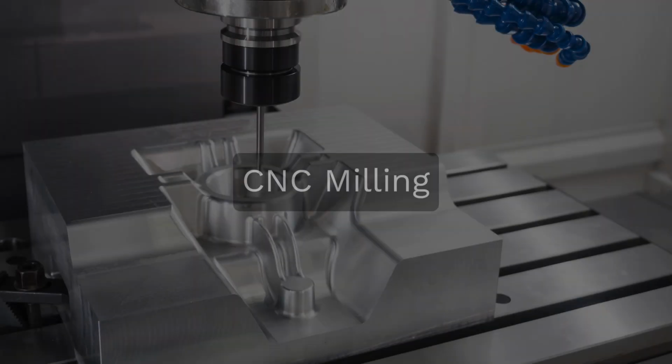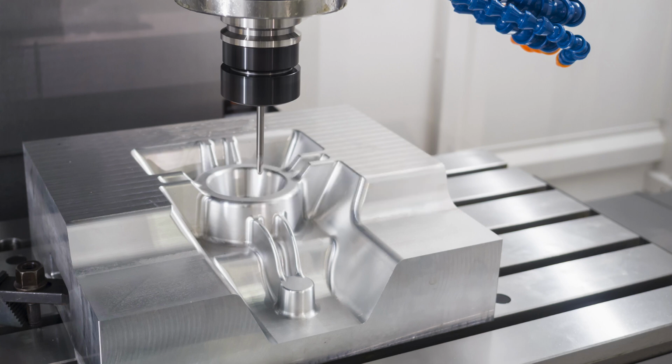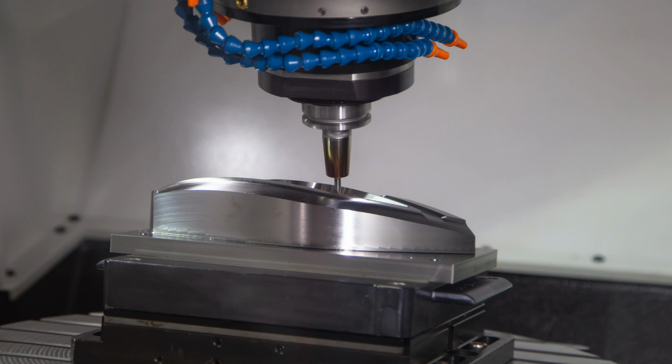And then moving on to the final manufacturing technology which we will be discussing today, which is CNC milling, so computer numeric control milling. And this is a very simple method where you simply take a block of material, usually wood or aluminum, and then you start milling away the material that you don't want until you have the desired part. In general, CNC milling results in a quite high per unit cost due to the amount of time that it takes to mill out one part.